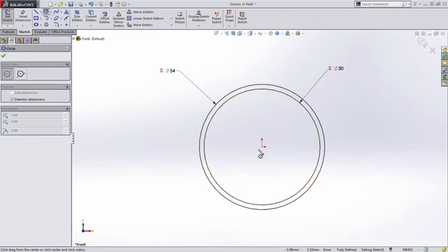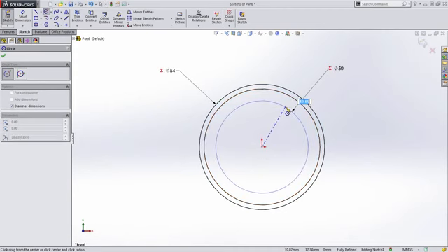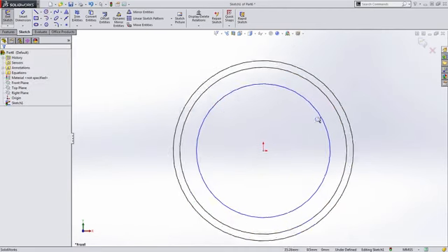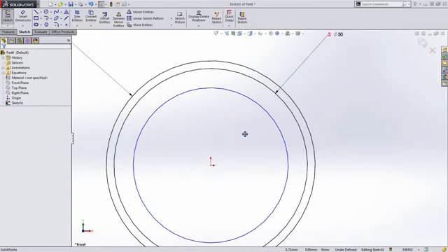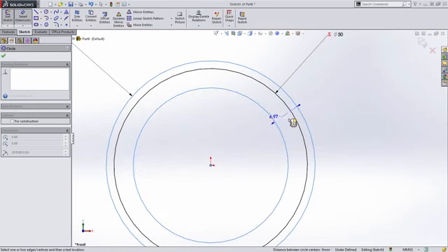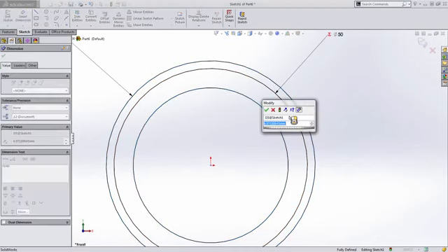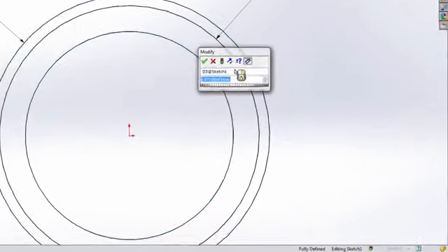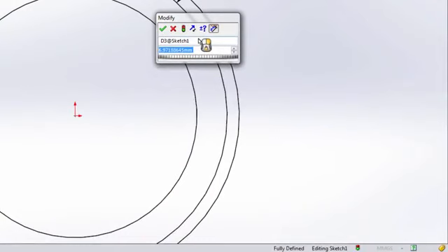The last value we want to capture is going to be the root diameter, and in our case, we're going to be incorporating clearance. So we're going to do this by solving for the whole depth, from the outside diameter to the root diameter itself. Now, if you wanted to design this line to line, for instance, you could double the addendum value, but as I mentioned, we want to incorporate clearance.